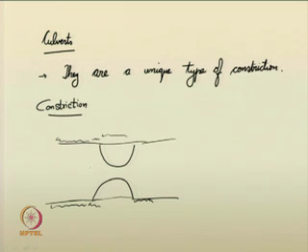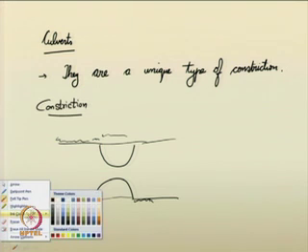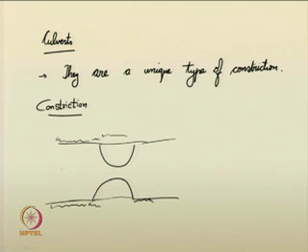So, here the natural drainage path, water was flowing in this much width, say B1 here, and all of a sudden it is getting constricted to another width B2, then it is coming out from that constriction. Such constrictions are provided in many engineering projects. So, culverts are also a type of constriction.